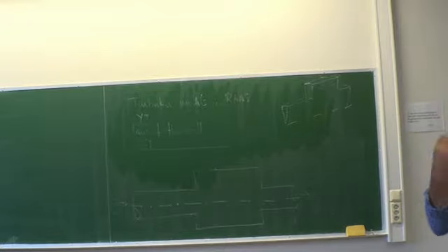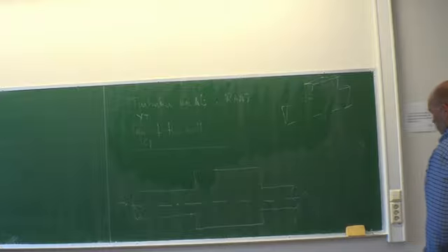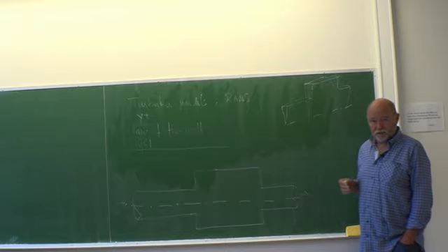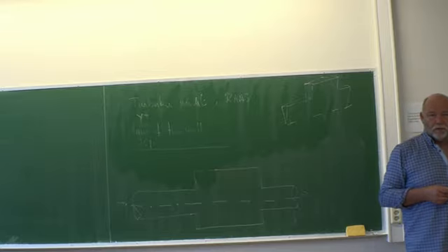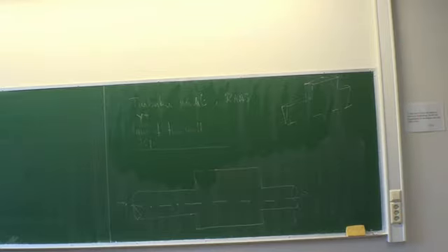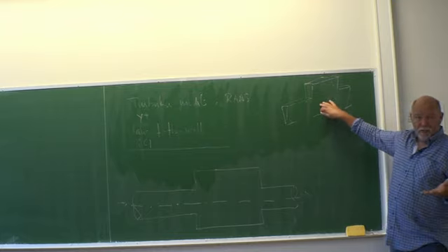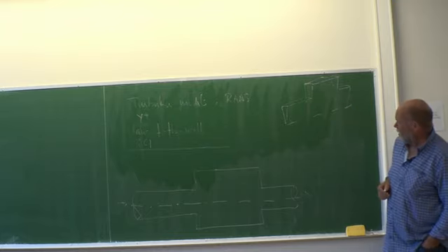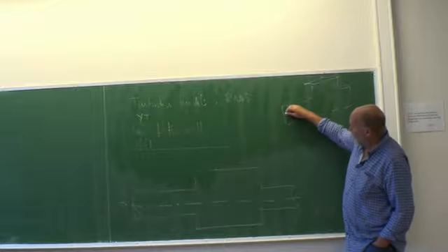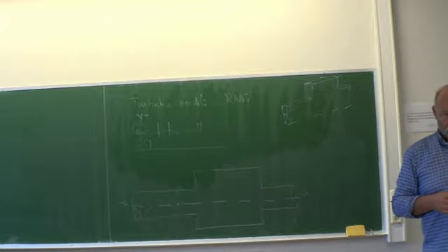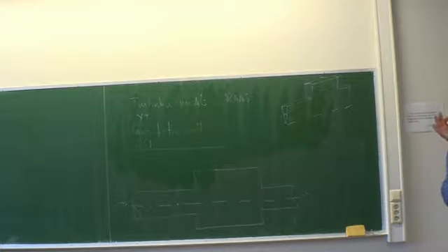I will give you such a mesh. I will do it quite crudely. So obviously then you have to change the dimensions here to get a reasonable simulation out of it. But I just give it to you as you see how such a mesh can be used. Normally they say this angle here should be quite small, 5 degrees or even smaller. So if you overdo it, then it won't be representative anymore.